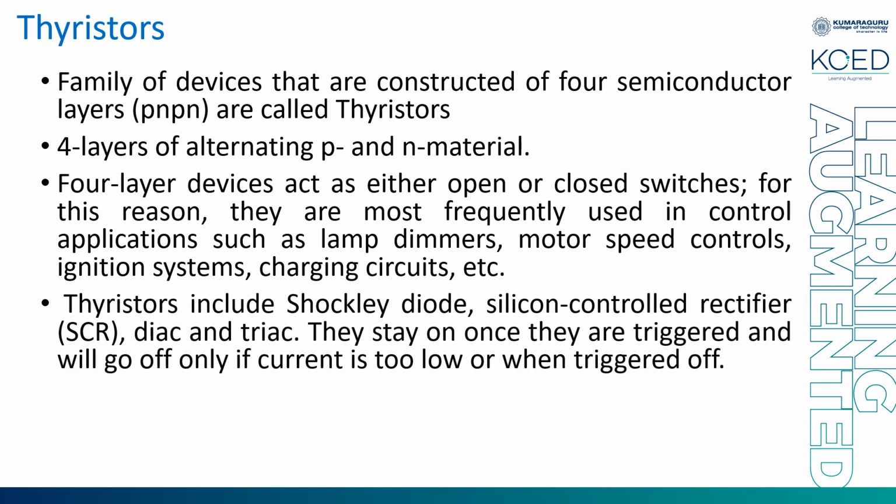We have different types of thyristors. The basic PNPN diode or Shockley diode, silicon controlled rectifier, diac and triac. These are the main types of thyristors. A few are with a control terminal and a few are without a control terminal.